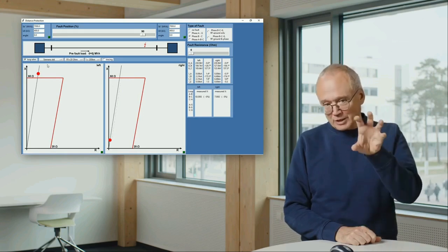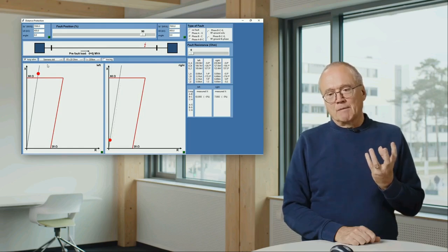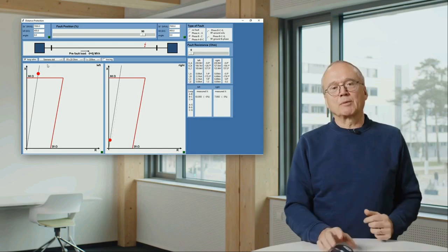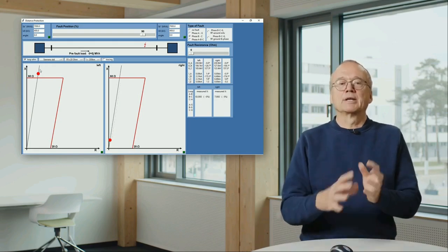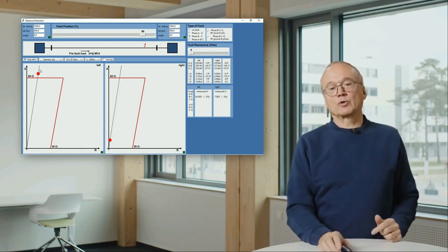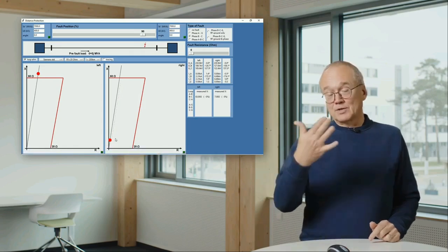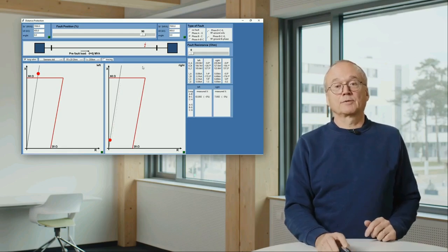That means we have to keep in mind that with this setting of 85%, we have the problem that at the end of a line there is a certain part where, at least from one side, the fault is not tripped. The other side, in this case the right relay, would of course trip the fault pretty fast.